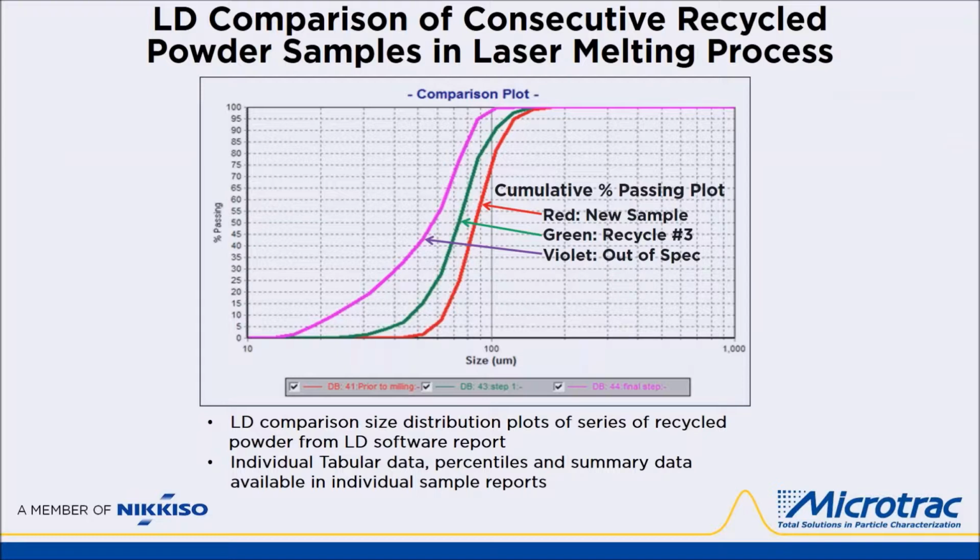This is a comparison plot report available in the laser diffraction software for comparing size distributions of recycled powder streams in an SLM process on one graph. The comparison plot is a way to spot if the recycled stream has become too fine for continued use.